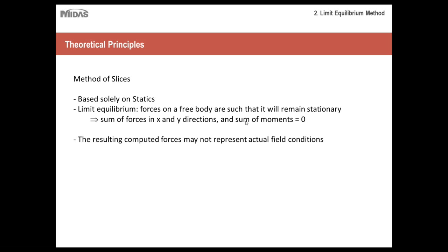And then the resulting computed forces may not represent the actual field conditions. That's another important thing to keep in mind: if, for example, you check the forces acting on those slices, just keep in mind that there are various assumptions made when doing the limit equilibrium method, which can lead to forces that may seem erroneously high or erroneously low.